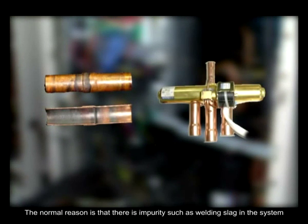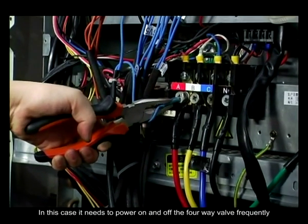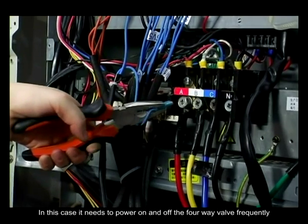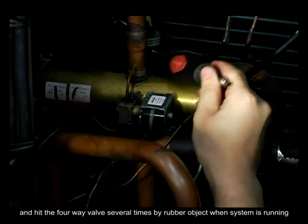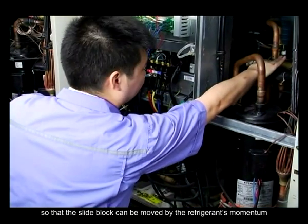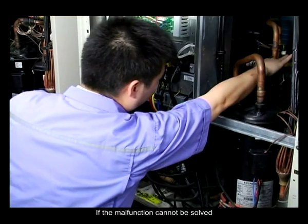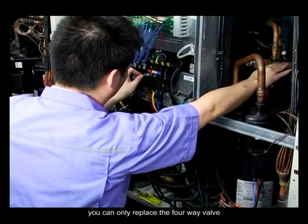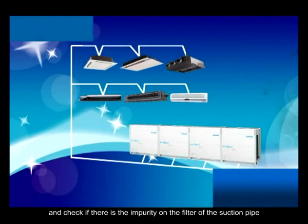The normal reason is that there is impurity, such as welding slag, in the system, and the impurity blocks the valve or slide. In this case, you need to power the four-way valve on and off frequently and hit the four-way valve several times with rubber objects while the system is running, so that the slide block can be moved by the refrigerant's momentum. If the malfunction cannot be solved, you can only replace the four-way valve and check if there is impurity on the filter of the suction pipe.